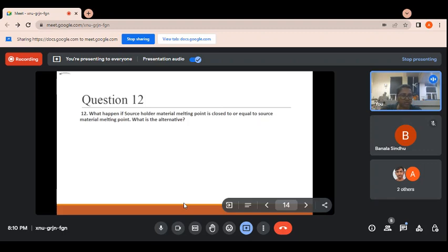And when it etches in all directions, like here the silicon dioxide is present, when we dip the wafer into the BHF solution, buffered hydrofluoric acid, in all directions it is etched out. So this is the example of isotropic etching. And when we go for silicon etching using the TMAH solution, in a particular direction, like this type of shape is present and here the diaphragm is present. So in a particular direction when it is etched out, it is called anisotropic etching. So is it clear to you?